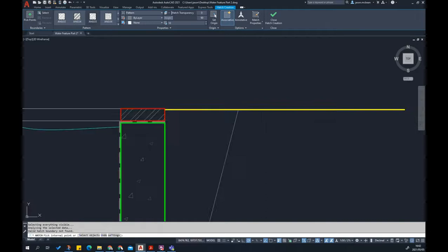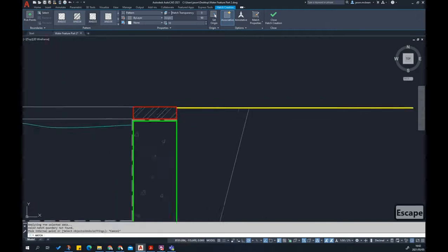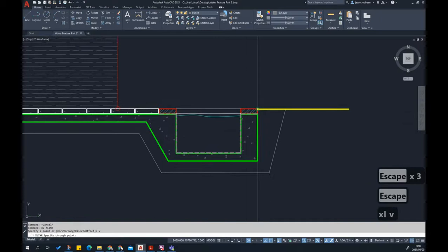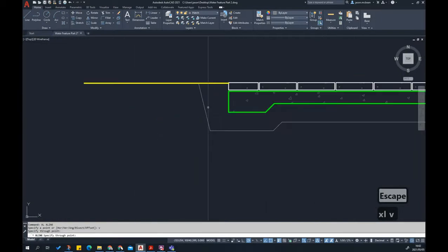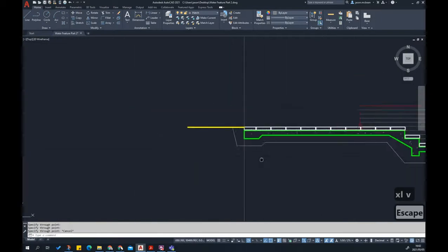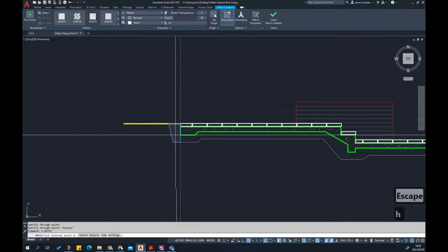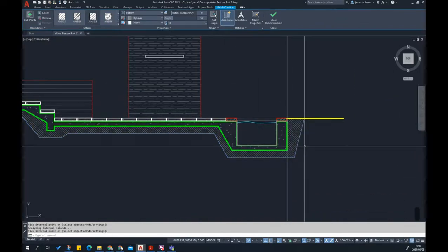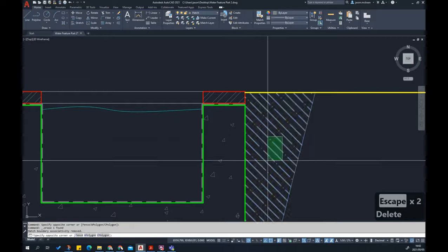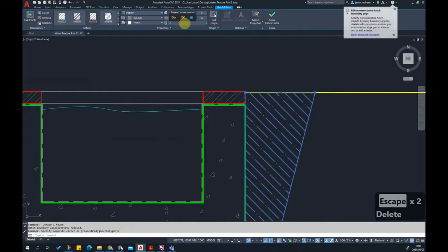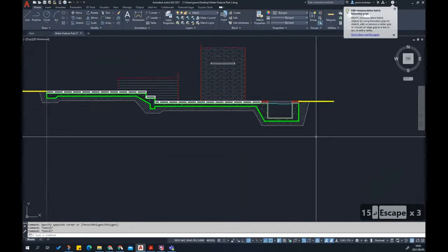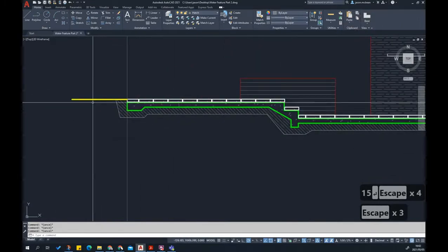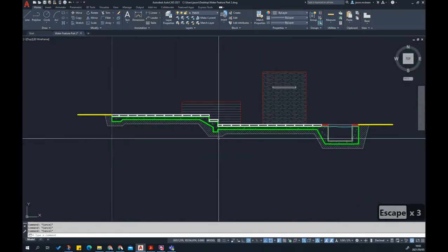Okay, so here we've got a hole. We've got some holes here. Here we just need to start using, so construction line, vertical, put one there, I'll put one there. That'll sort it out. So I'm going to go hatch, there, and there. Done. Okay, this I can scale up by 2 maybe, make it 15. Okay, so that's that kind of layer. That's that line there. Now the rest is just going to be natural earth.